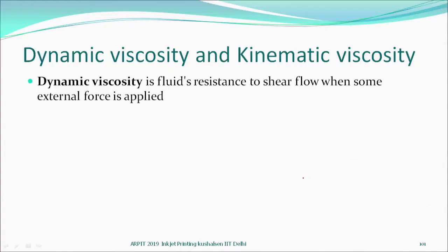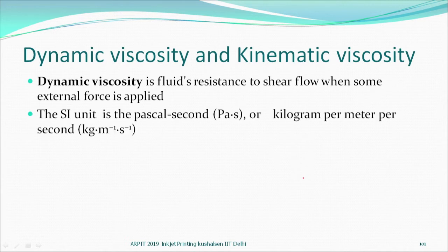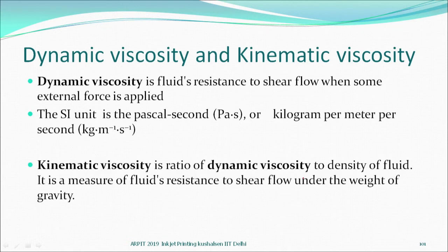These terms are available in literature, which people will be discussing. Those who make ink will be worried about these things, and so they must know. There is something called a dynamic viscosity, which is the resistance to shear when an external force is applied. The units are kilogram per meter per second, or Pascal second. Then there is a related thing which is called the kinematic viscosity, which is the ratio of dynamic viscosity to the density of the fluid. The density term has come before also.